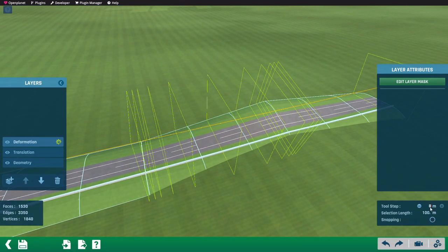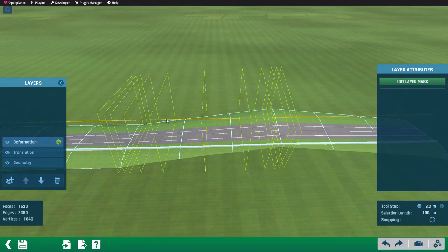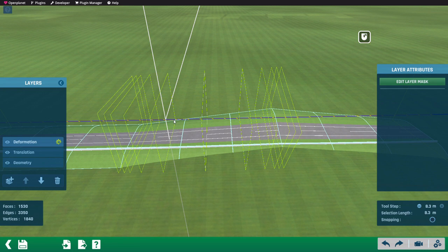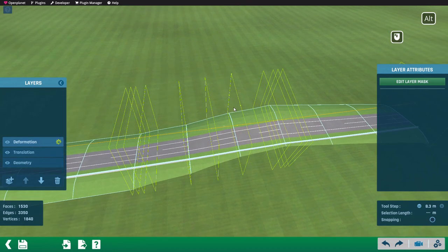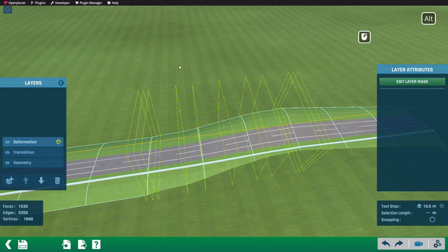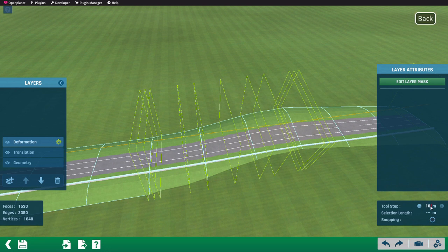The central control frame does not need to be shifted. The results of the formula for the four pairs from inside to outside are 8.3%, 10.5%, 9.8% and 8.2% of the transition length. All shifts have to be done towards the middle. This partition already creates a smooth sine curve-like transition, but you can do this with even more control frames if you want. Just calculate the needed shift with the formula.